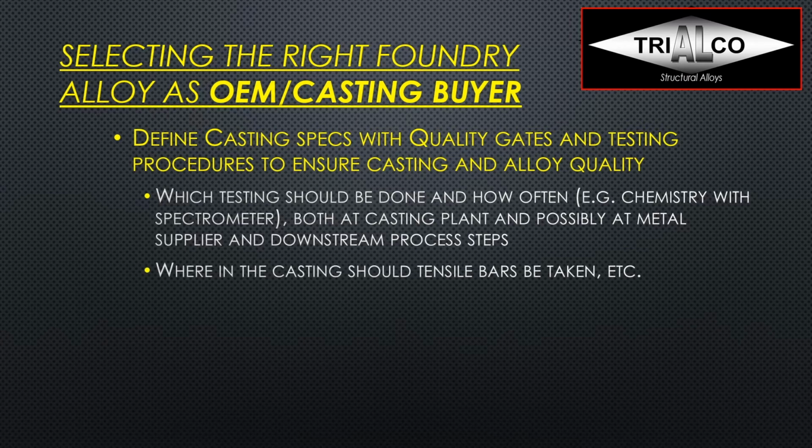Where in the casting should the tensile bars be taken? So you specified your mechanical properties, and I said before, the mechanical properties will never be the same everywhere in the casting. So you really need to define, okay, these are the areas that are very important. Those might be the areas that are exposed to something. This is where it's mounted. This is where it's going to be riveted. So this is where I really need my 10% elongation. And here I have an area that is just there and there will not be much tension or pressure on it. So there I can live with lower properties.